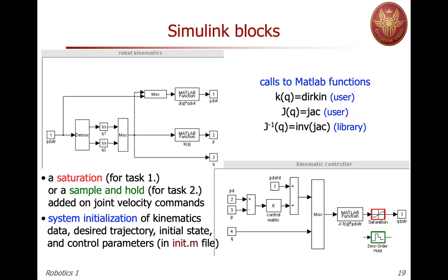There are special commands, the sim command, that will start the Simulink block without the need of opening and updating this. This has two advantages. It's parametric. If you decide to change some value, and this value appears in several points, then in this way it will update it everywhere.